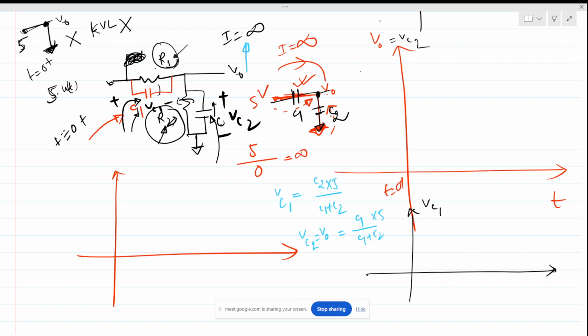So this is the normal capacitive divider, we all know, like the opposite of the resistive divider. Now Vout will suddenly jump from 0 to this voltage. Let's make this clear. Simplification: C1 equals C2 equals C. So now this 5 volt will divide into 2.5 and 2.5, right?